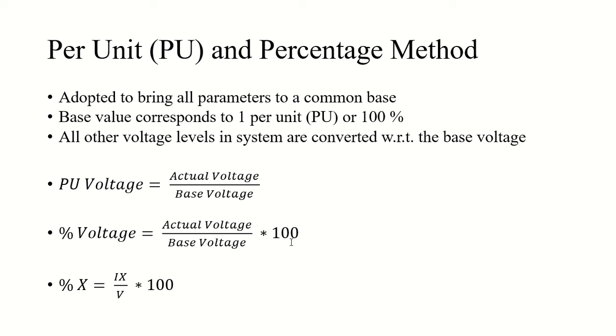These values are mentioned for the calculation of short circuit faults. If you want to calculate the short circuit fault, then we use these percentage reactance values.